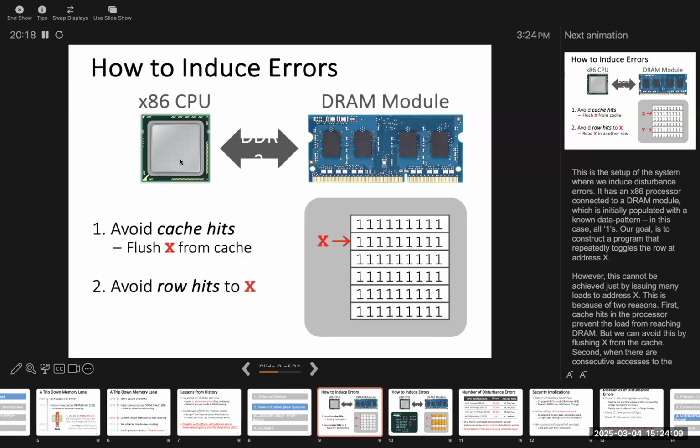So from this whole row, you get all of the data into the row buffer, and then you send back to the CPU only 64 bits. But why do you put the 8 kilobytes in the row buffer? Because you are anticipating that the next data that needs to be read also belongs to the same row. You don't want to activate this row and read it again.